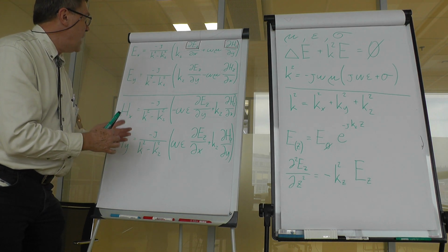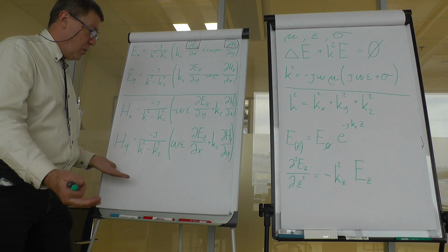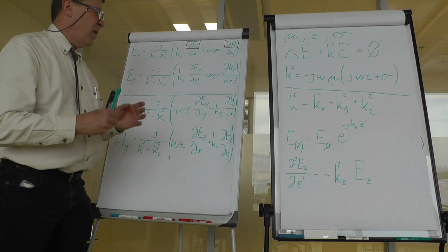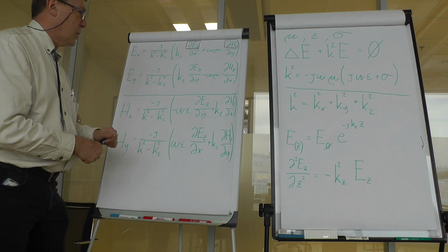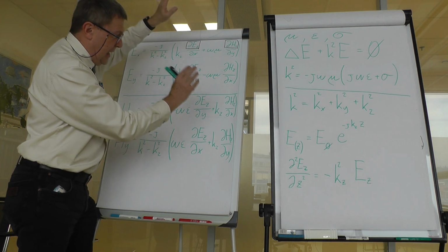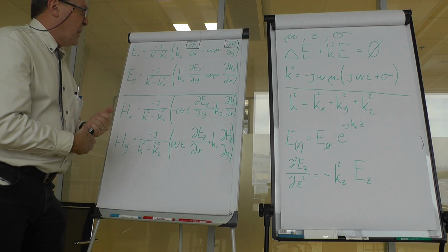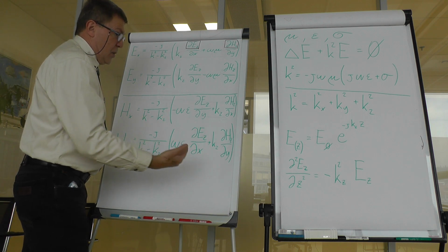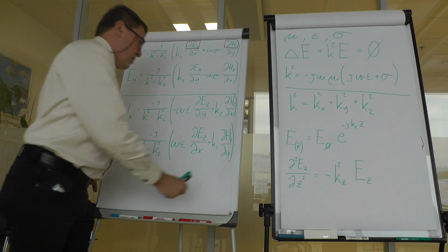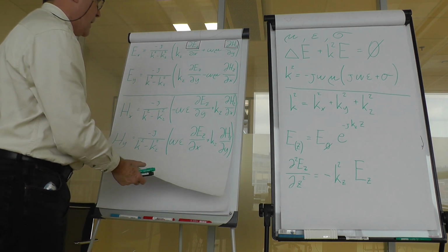So we now have a means to find out this equation or the solution within only 2 components, and for the sake of simplicity we will start with one of the modes, because those are 2 independent tasks: transverse magnetic waves, transverse electric waves. So for the beginning we can start the job with setting Ez to a small value, then Hz to 0, and vice versa, and we can do the solution.